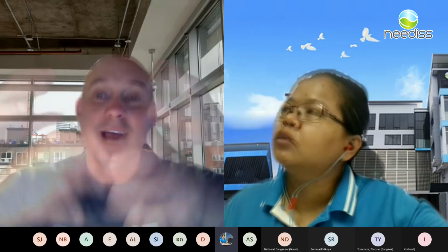So if you're an experienced stack tester and you go to a location, you can typically tell if you have yaw, pitch, cyclonic flow, anything like that in a stack. One good giveaway is a lot of vibration on the stack. The stack is moving constantly because the air is bouncing back and forth like this.